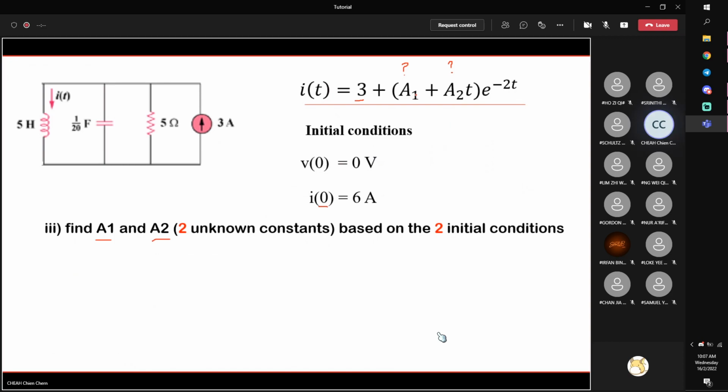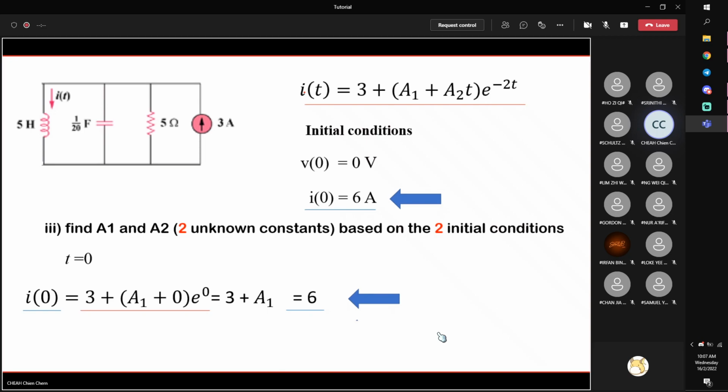But the other initial condition is voltage. It's not the current, so therefore we need to relate to the current. So we leave it to later, which means that you start from this one first. It's easier because now you're considering current. Like just now your classmate raised, how about voltage? If you consider voltage, then you start from the first initial condition. Put t equal to 0. Check the values of that. At t equal to 0, that must be equal to your initial condition.